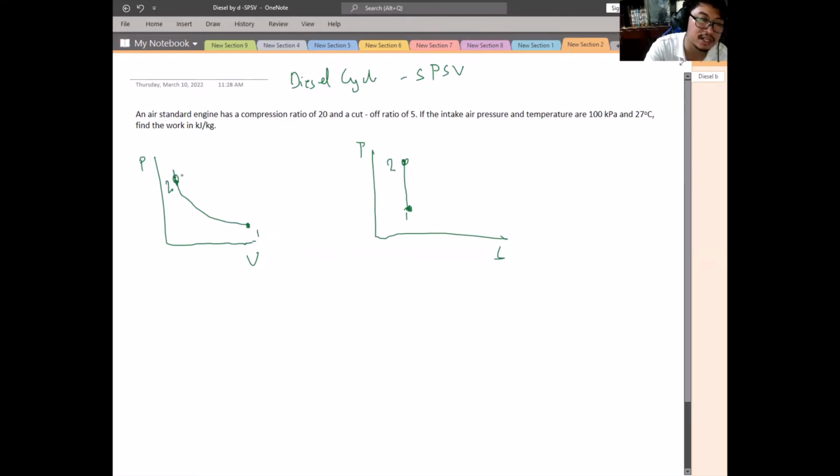That is a constant pressure heat addition. Here, heat is added, or it is the start of combustion inside the piston cylinder. That is why this part is heat addition, 2 to 3. In the TS diagram, it is a constant pressure process, heat addition, raising the temperature and the entropy. Okay, next is point 4, the expansion.